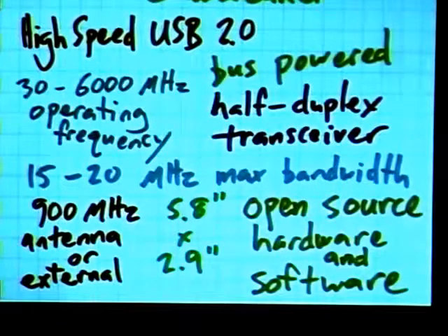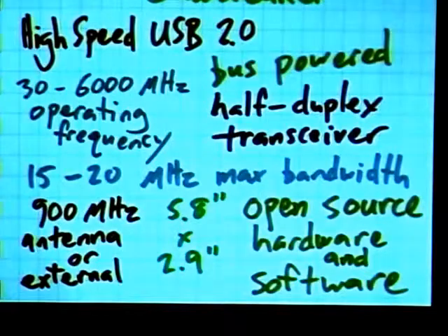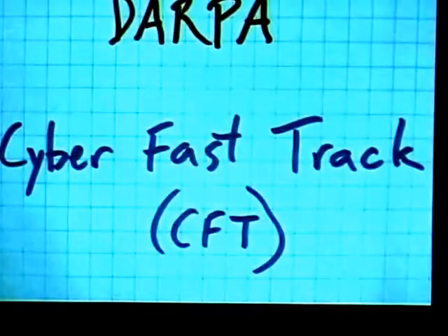It can transmit or it can receive, so you've got options there. It runs off of USB, and I don't know, have you tested the total power consumption at the moment? I haven't, not recently. So, of course, we're trying to keep it within the USB 2 limitation of 500 milliamps over the USB. So far we haven't had any problems, but we should probably do a formal test of that. And most importantly, everything about the design is open source.